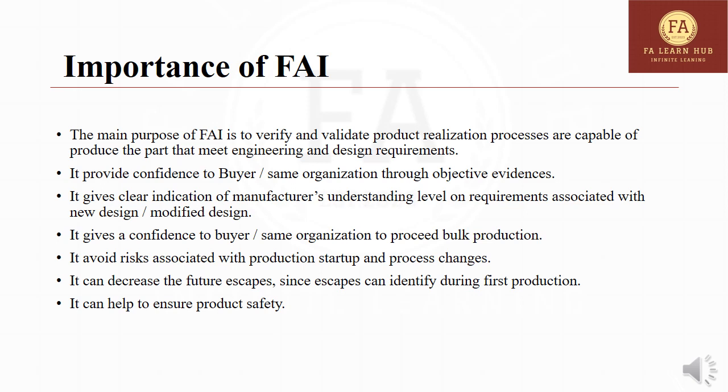Consider a PCB manufacturing company, ABC Aerospace. They got a new Gerber and a test document from one of their customers. They have to manufacture the PCB as per the Gerber and test the PCB as per the test document. The test document indicated that the bareboard test shall be conducted with 250 volts in power lines and 50 volts in signal lines. Bareboard test is a kind of automatic electrical test.